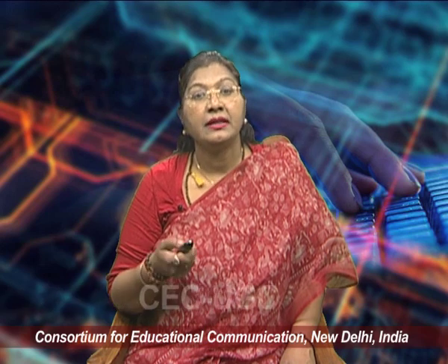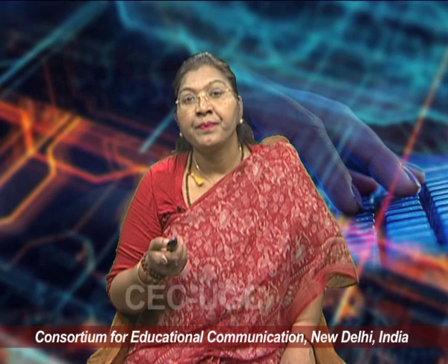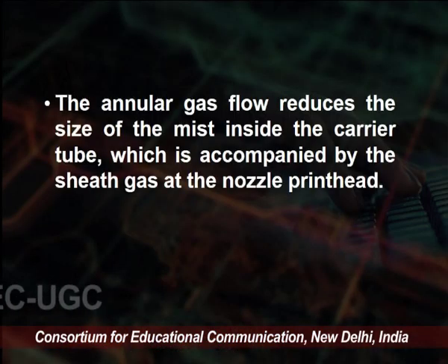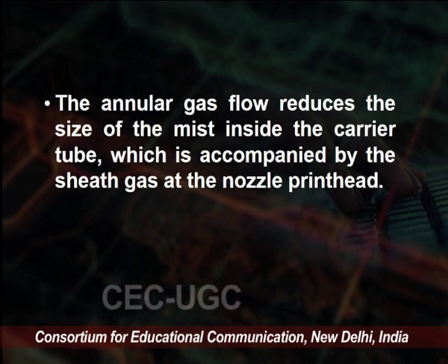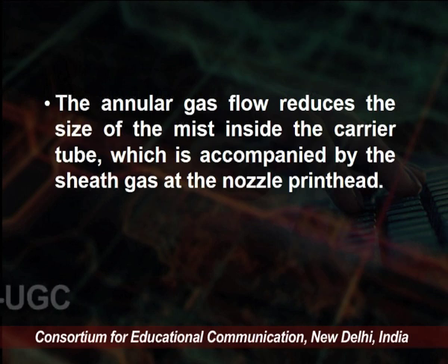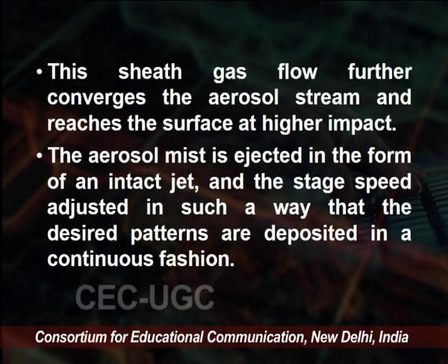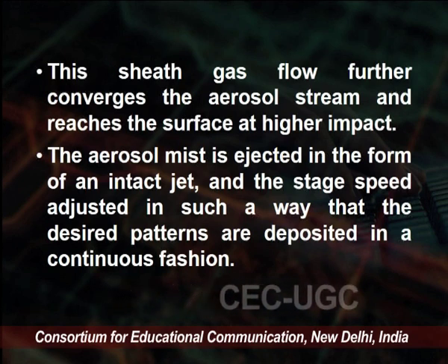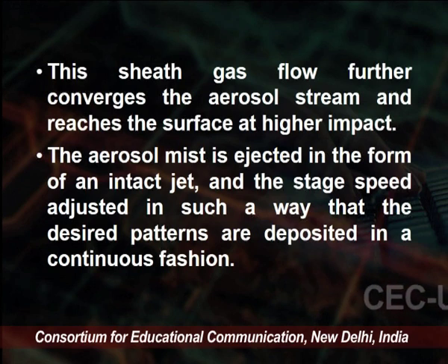For example, the 10 micrometer, for instance. So, both techniques are used accordingly, but the best technique of these two is the ultrasonic aerosol technique. The gas flow reduces the size of the mist inside the carrier tube, which is accompanied by the sheath gas at the nozzle. Now this gas flow further covers the aerosol stream and reaches the surface at a higher impact.